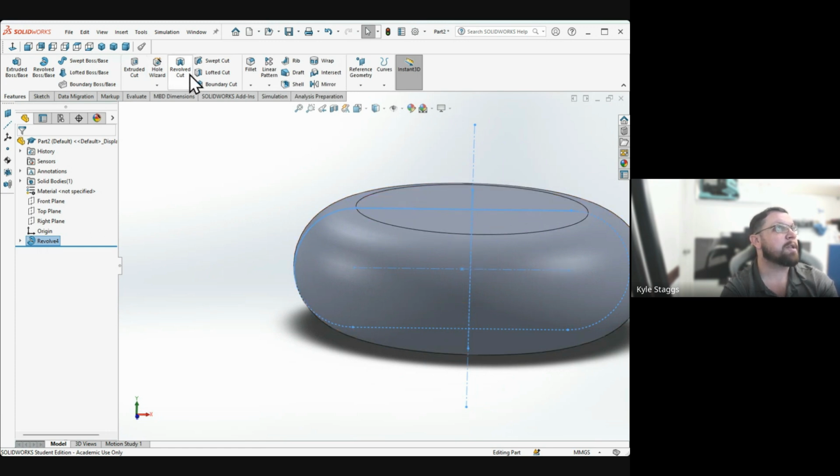There's another operation that is the opposite of the one that you just did typically. So there is an extrude, which means to add material, like you're 3D printing. There is an extrude cut, like you're drilling or making a hole, or cutting with a router or whatever. So you can add material based on the shape of your sketch, or you can take away material and cut away material based on the shape of your sketch. Similarly, you can add material like a 3D printer revolving, or you can take away material like a revolve cut.